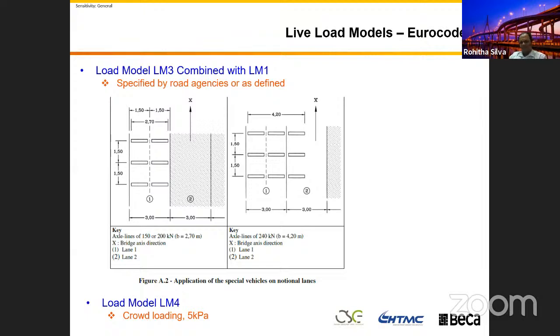Like they say it's a 25-meter bridge, you don't want to worry about the other vehicles on the 4-lane bridge, the rest of the area, when you design for heavy vehicle load, because it's a short period of time, short length. But if you are designing a highway infrastructure project a couple of kilometers in length, you can't say my bridge number 1 is this one, bridge number 2 is that, bridge number 3 like that.